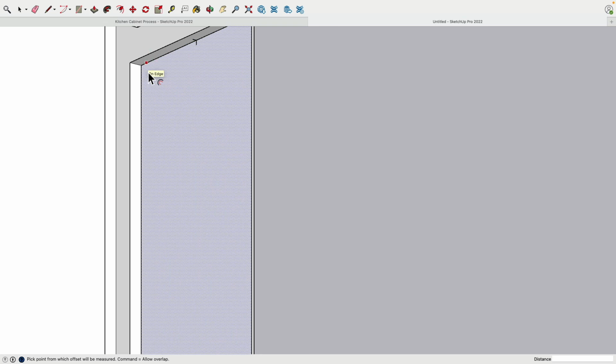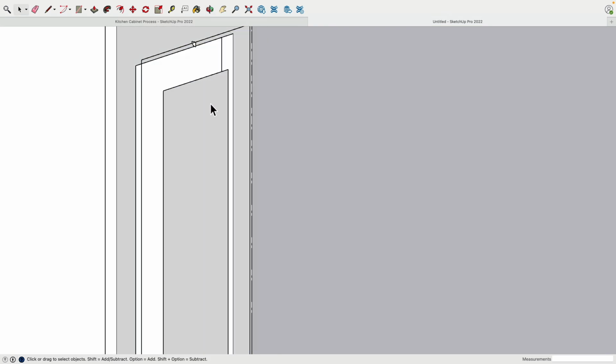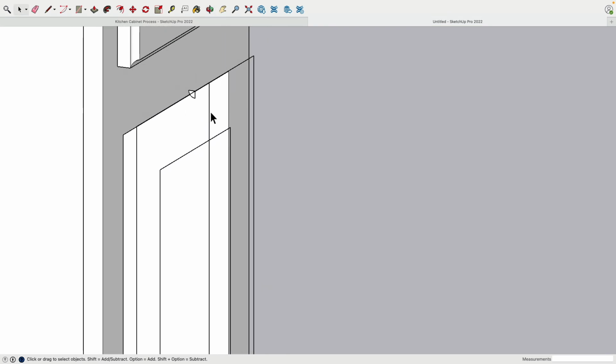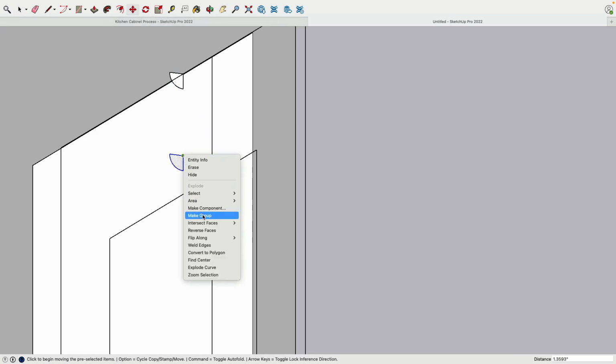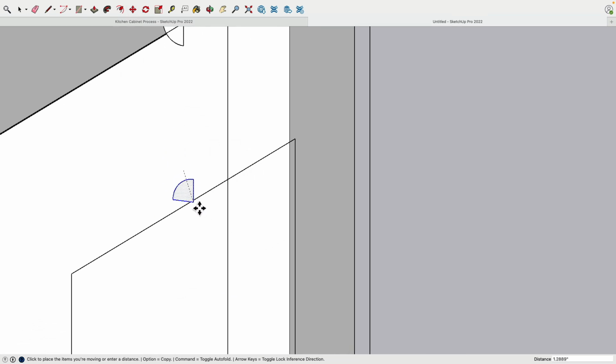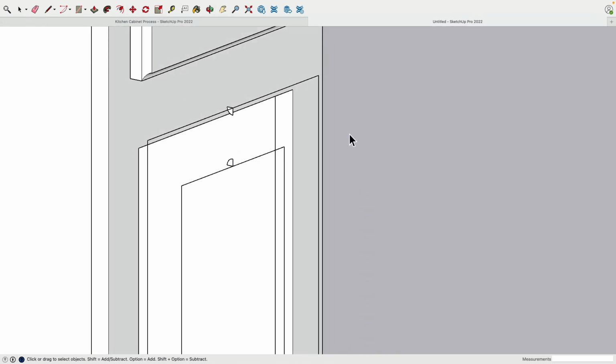So nothing selected, I pressed escape. I do an offset of this interface, and let me now show you. There you see what I did. So here we have path number 1, path number 2. Now this piece, double click, make a copy, move this to here, right click, flip along blue direction. Yep, and then this, where's the midpoint? There it is. Very good.